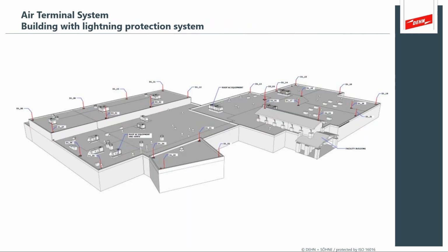Air termination system, the air terminal system. So Ben Franklin figured it out. You put up an air terminal, and it serves as a preferred attachment point for the step leader, that last striking distance where the lightning charge builds up over an area, and all of the objects, we saw that in some photographs last week, all of the objects send up little tendrils trying to reach out to that lightning charge, and one of them will attach.